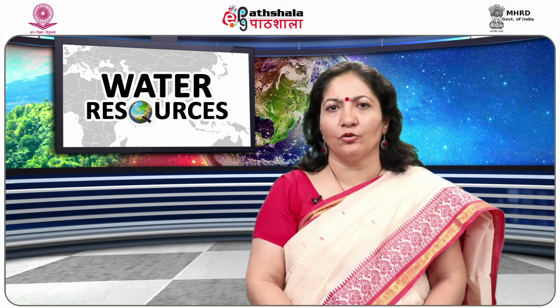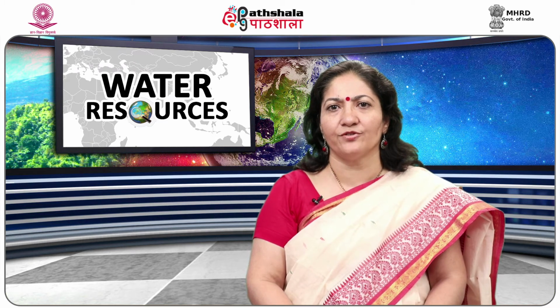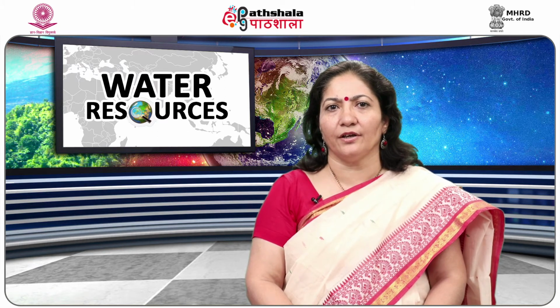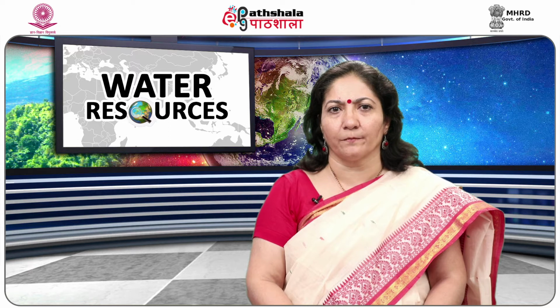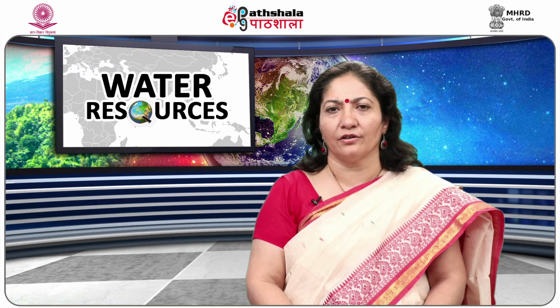Sand and gravel, on the other hand, make excellent sources of groundwater even though they have lower porosity than clay, due to the high specific yield which allows the groundwater to flow to wells. If rocks such as limestone and basalt are well weathered and highly fractured, they make good quantities of groundwater. Specific yield is defined as the ratio of the volume of water that drains from a water-filled rock due to gravity to the total volume of rock.